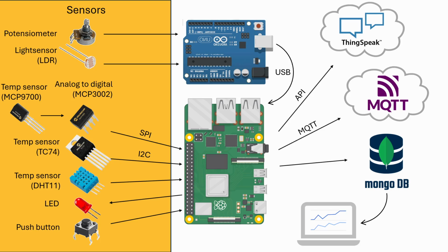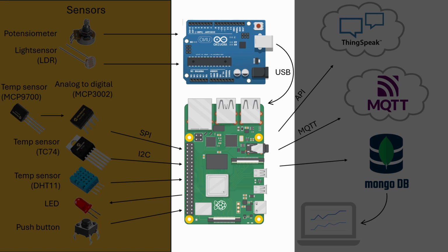The second part of this diagram contains the Arduino and the Raspberry Pi. The only reason we are using the Arduino here is because it has analog input pins. The Raspberry Pi is the most important part in the project because it's the only part that all the data flows through. Its job is to read all the different protocols, collect the signals together, and push the data out.